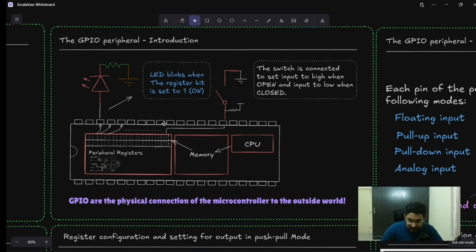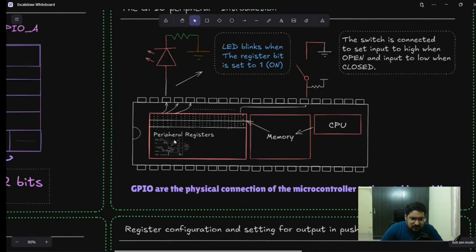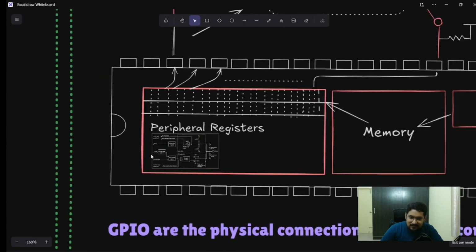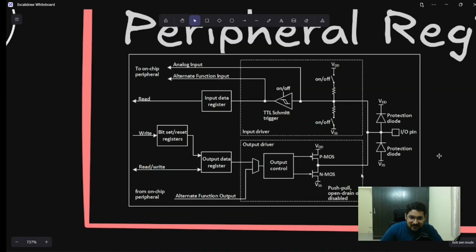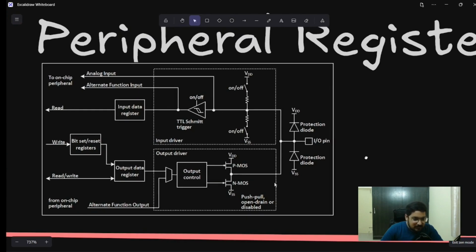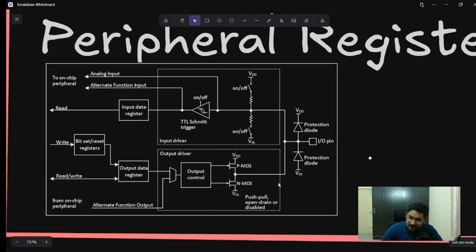All right, fair enough. So if you zoom in, we see that the GPIO peripheral is quite a complicated beast. It's not so simple like Arduino where you just set something and write the value. Because every other peripheral that has to talk to the outside world needs access to the GPIO peripheral, be it UART, SPI, I2C.